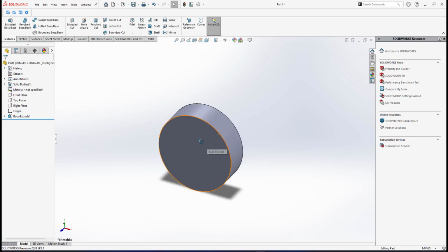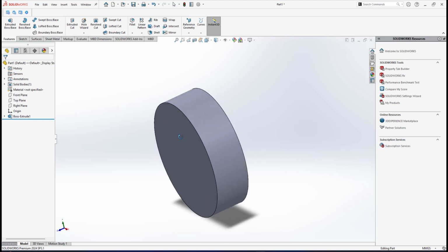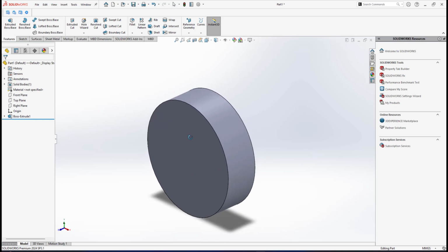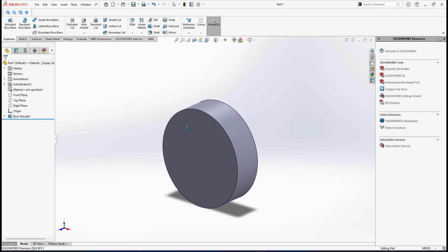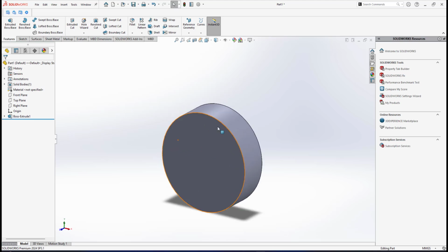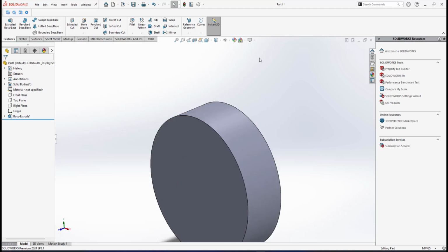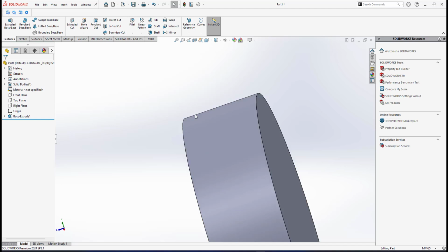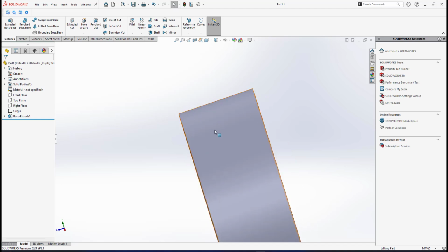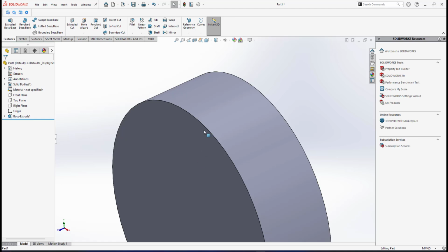Alright, my approach is different from what you have found on YouTube on how to create a fan blade, because I think mine is more accurate in terms of controlling the curve of the blade rather than using sweep boss and twist angle. Before that, since the thickness is 8, I create another plane, because I will make the fan blade as a thin surface and then thicken it to meet the thickness. The fan blade thickness is not as long as this 8 mm thickness, so I make it a little bit inside.